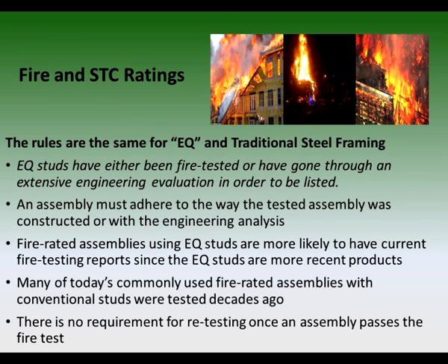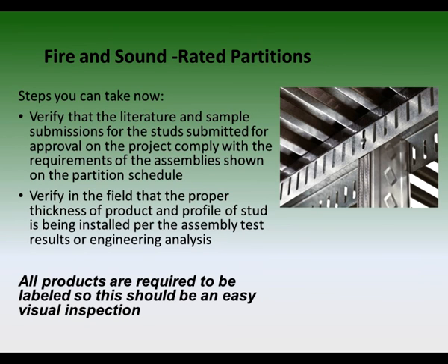What we say here about fire-rated assemblies also applies to STC ratings for acoustical requirements. The important point is that the as-built assembly must match the tested assembly or engineering analysis to achieve the listed STC rating. These are a few suggestions for making sure you meet fire and sound criteria.